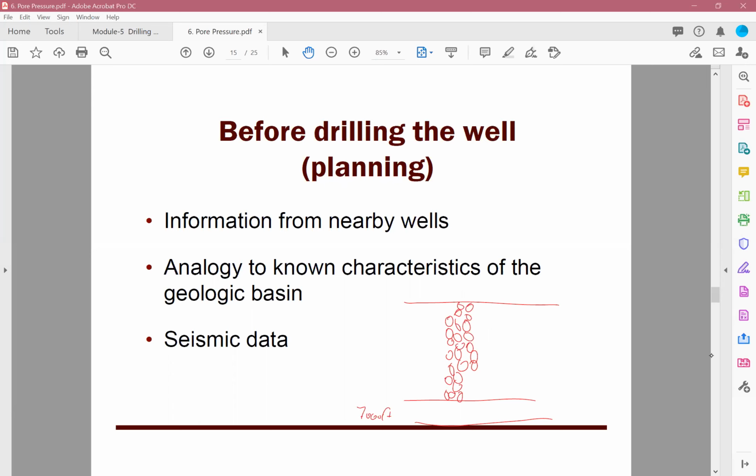There are many reasons we discussed last time, but one of the main reasons is that when you have a normal pressure gradient, which means that the pore pressure gradient is constant depending on the location, it could be somewhere between 0.433 psi per feet to 0.5 psi per feet. Depending on which area you are, most likely it's close to 0.433.